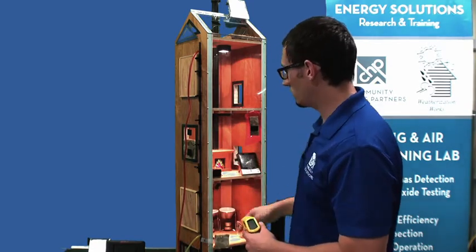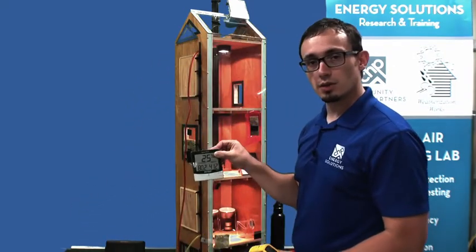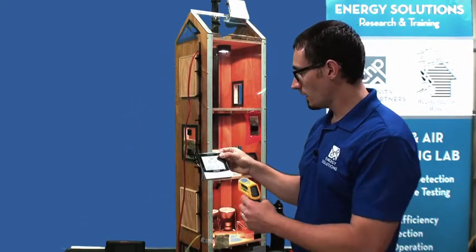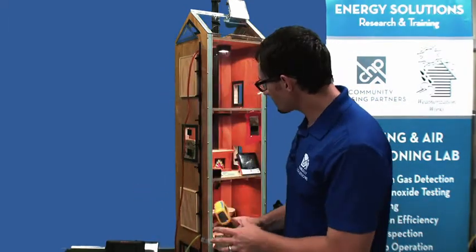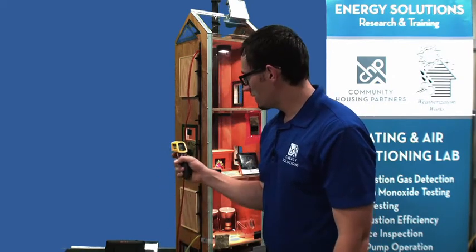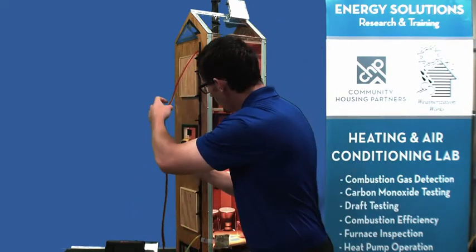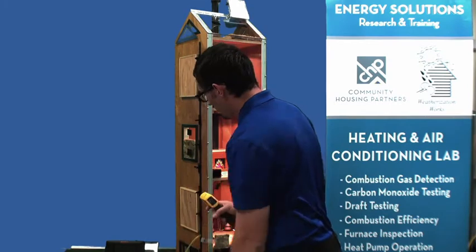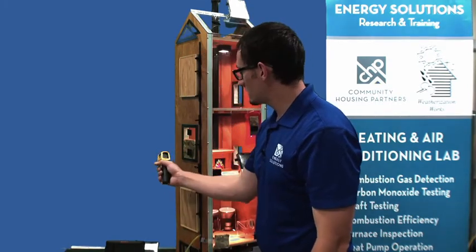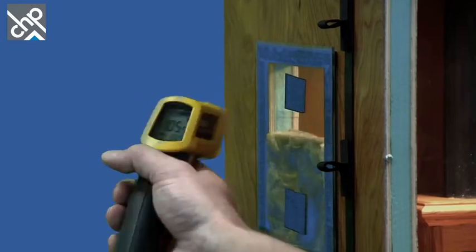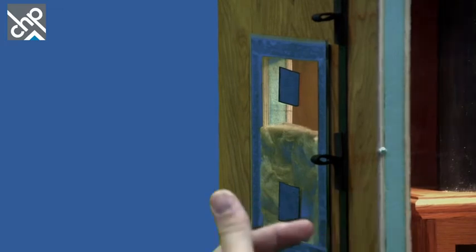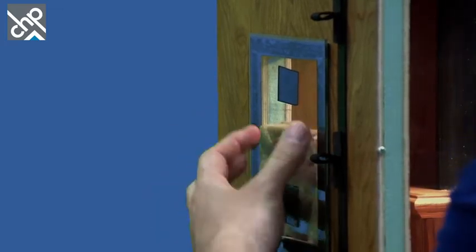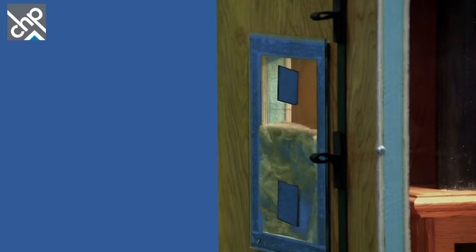We're at about 25% relative humidity outside the house, and 10% relative humidity inside. So we've got some insulation down here. That surface temperature is at 88 degrees, holding steady. Then let's just get this thing out of the way here. So 88 degrees, holding steady. This upper one here, 105 degrees. So you can see that insulation is doing its job, and it's going to keep the lower half of this a lot cooler than the upper half because it doesn't have any insulation.